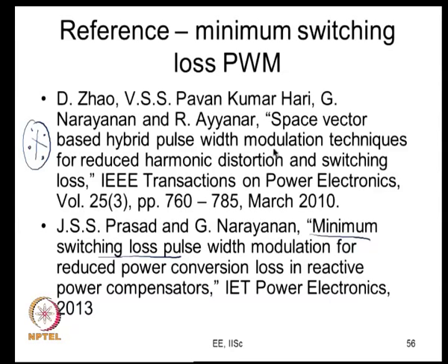So, this actually tells you how to derive a minimum switching loss PWM, which is a combination of all these sequences: four advanced bus clamping sequences, the conventional sequence, and the two bus clamping sequences. Using these seven sequences, there is a particular PWM method which minimizes the switching loss at a given average switching frequency. So, it is shown that this is an advanced bus clamping PWM method.